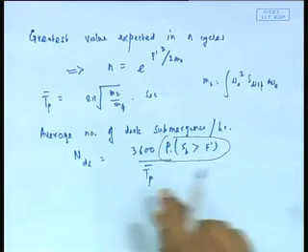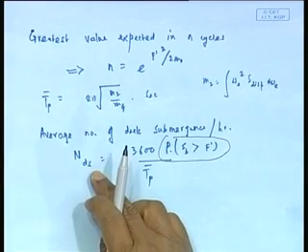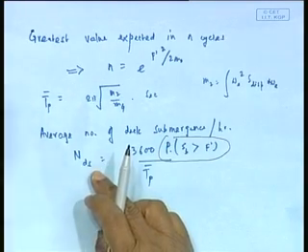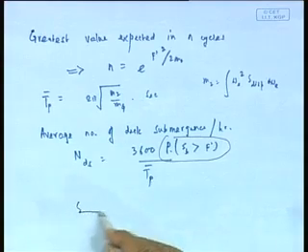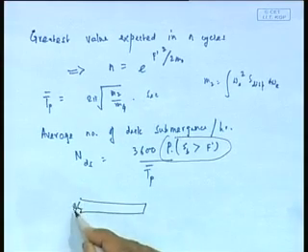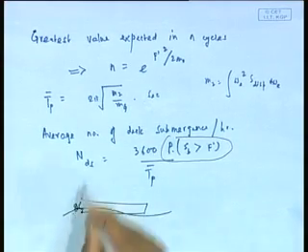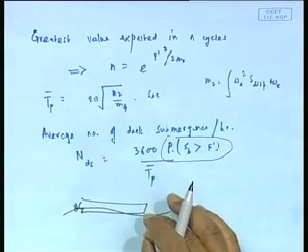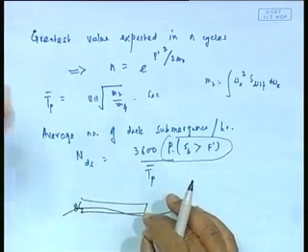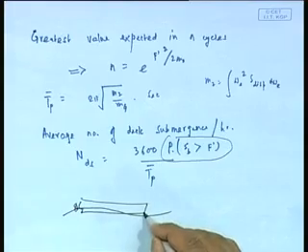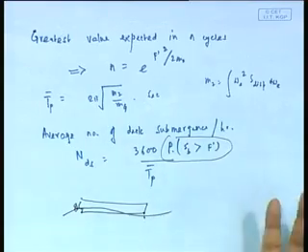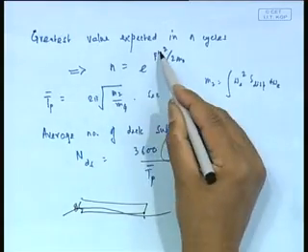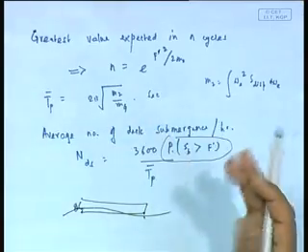Okay. Similarly, instead of deck submergence, I can say propeller emergence. Typically, for example, the ship is going like that, the propeller is here, and if the water is here, the propeller can also go outside. Same thing I can do. Exactly the same thing I can do for forefoot emergence, that is, this forefoot is coming out of water. Same relation, because all that will change is this f dash value, and the probability will change.